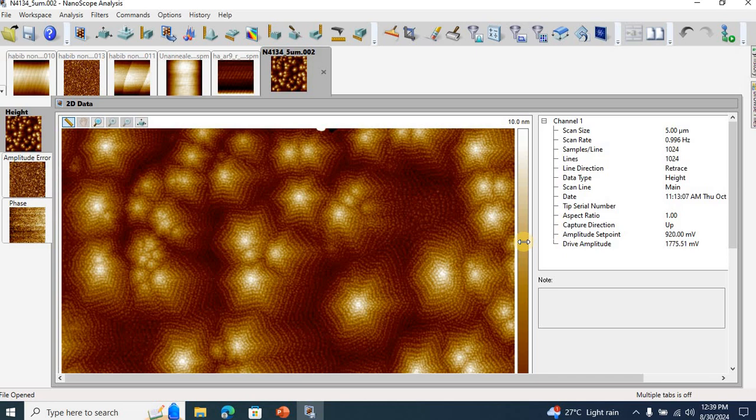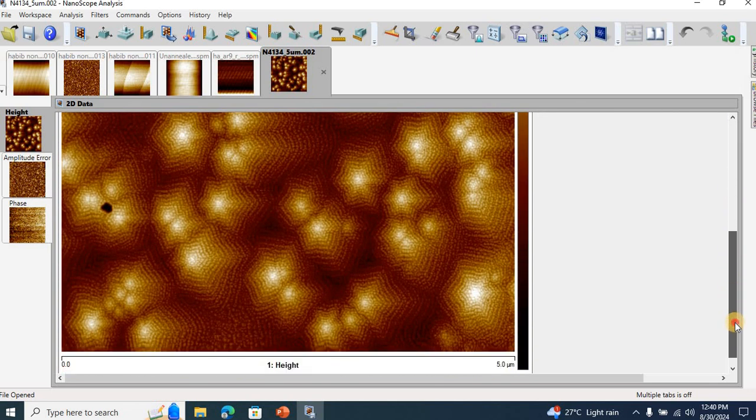Growing this quality indium nitride film is not an easy job, and you can see the spiral helix mediated step flow surface morphology with interlocking steps, wound around the threading dislocations over here. These points actually represent the mixed threading dislocations. The spiral helix are generally associated with mixed threading dislocations in molecular beam epitaxy grown nitride films under metal rich conditions. But this surface actually is a signature of a real high quality grown film,